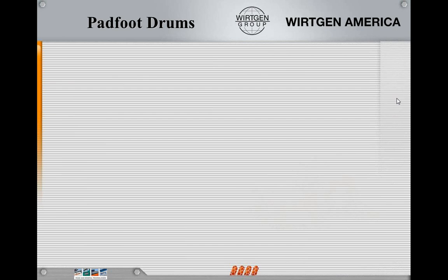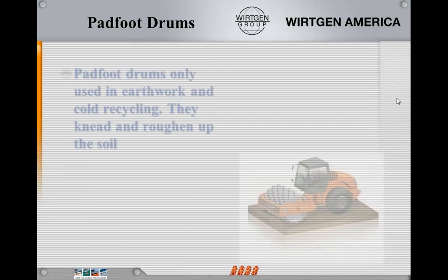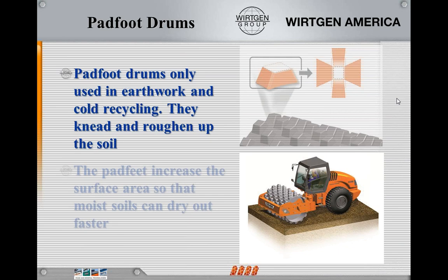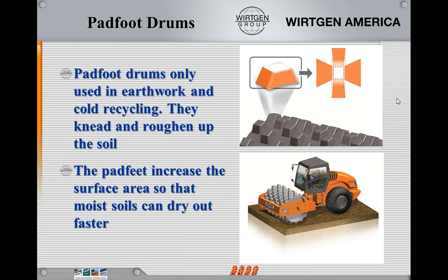Now, when we look at pad foot drums, they are used more in earthwork and for cold recycling. They kind of rough up the soil. If it's a higher clay content material, we can actually dry the material out based on the shape of that pad foot. Now, the reason why the pad feet are shaped the way they are is because it does increase the surface area of what we're trying to do.